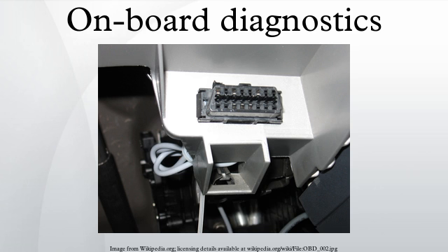OBDII is an improvement over OBDI in both capability and standardization. The OBDII standard specifies the type of diagnostic connector and its pinout, the electrical signaling protocols available, and the messaging format. It also provides a candidate list of vehicle parameters to monitor along with how to encode the data for each. There is a pin in the connector that provides power for the scan tool from the vehicle battery, which eliminates the need to connect a scan tool to a power source separately.